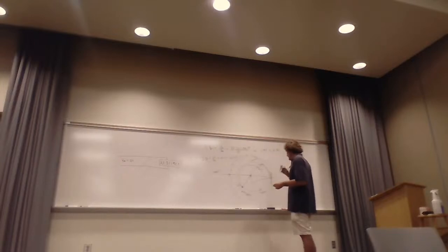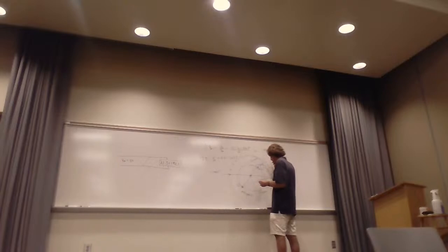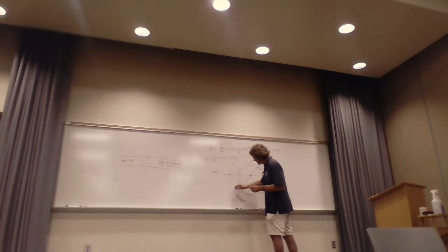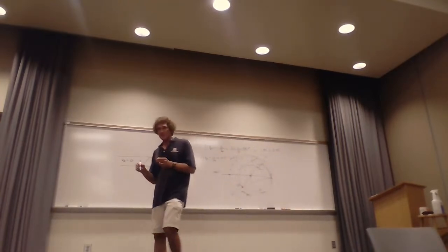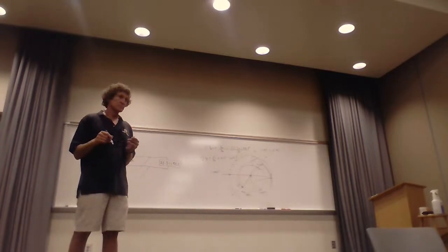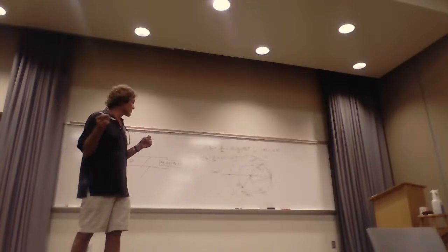I'm going to assume he took this point as the distance to the actual attachment point of the stub, but it doesn't have to be. So if you come here and just shoot a line here, then the distance that you travel is from here to here. Do y'all see that, class? Did he do it that way? Does anybody know? He has the open-ended stub length as 0.392 wavelengths.